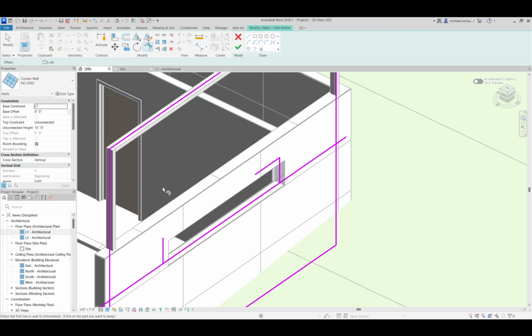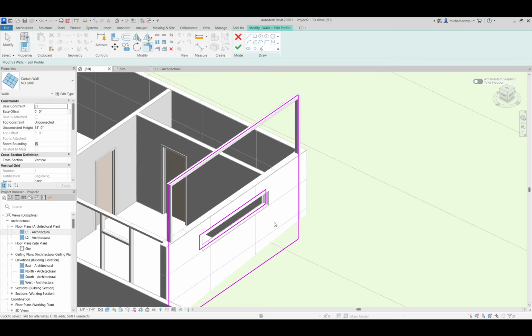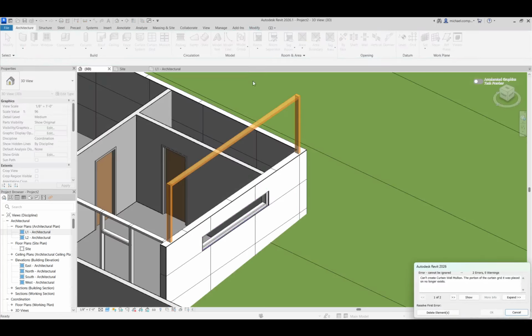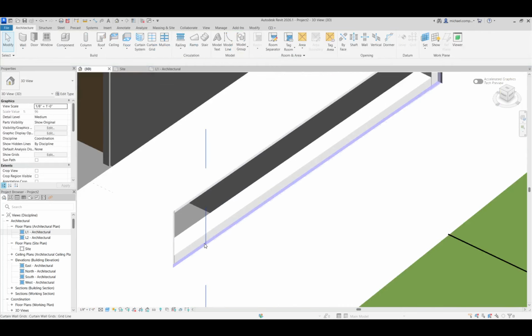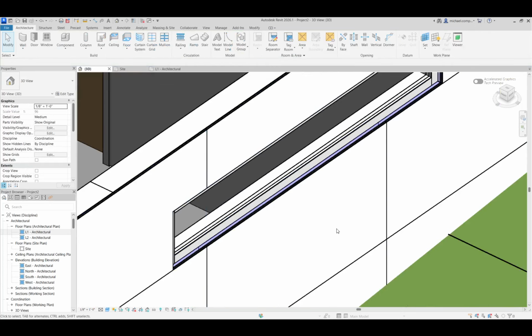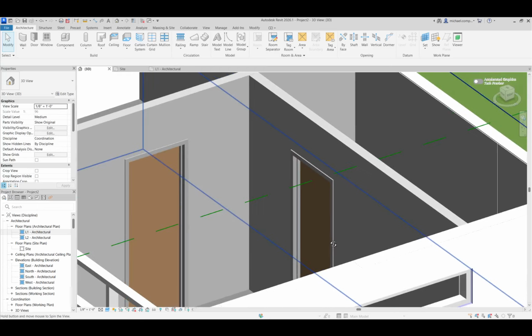And then I'm going to clean that line work up because it has to be a closed polygon, right? And then delete the exterior because I don't need those lines anymore. Hit OK. It's going to delete those mullions, and instead it moved those mullions to the interior, and now we have a window.